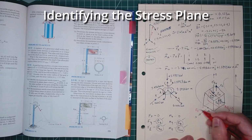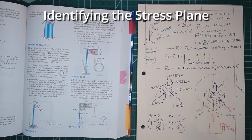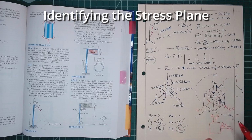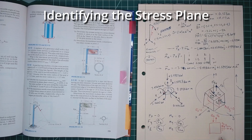There is no sigma, there's just no stress acting on that face of that stress cube. So both of those are 0. Since they're both 0, the maximum in-plane shear stress is going to occur where we have shear stress occurring. So that's why we're going to take this plane versus one of these other planes on that stress cube. So this is going to give us our maximum.